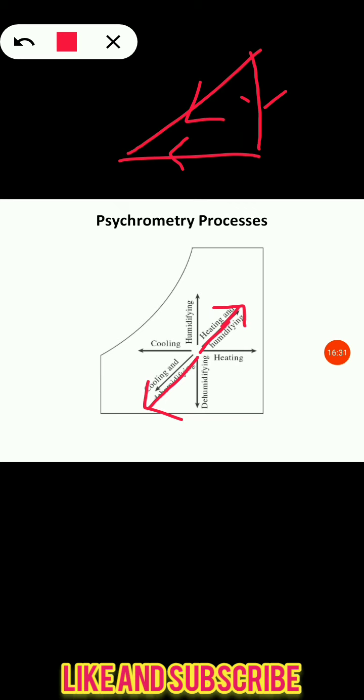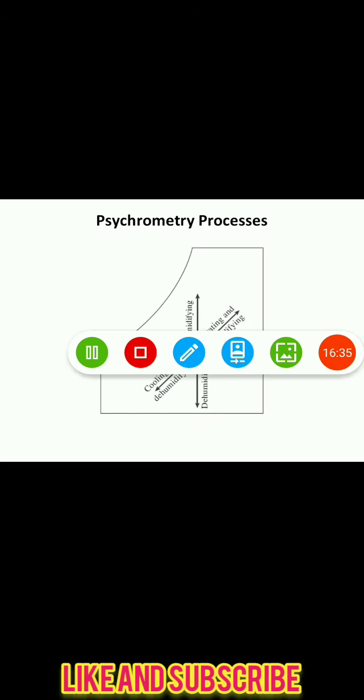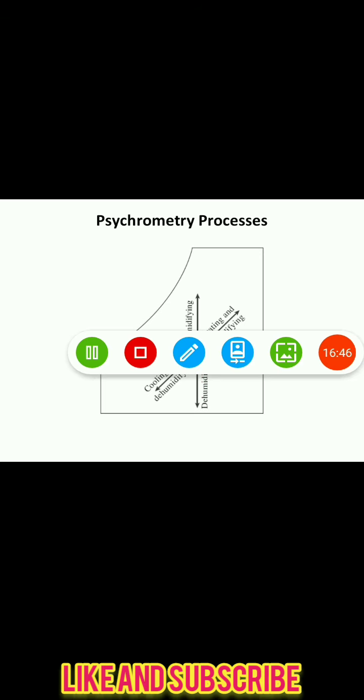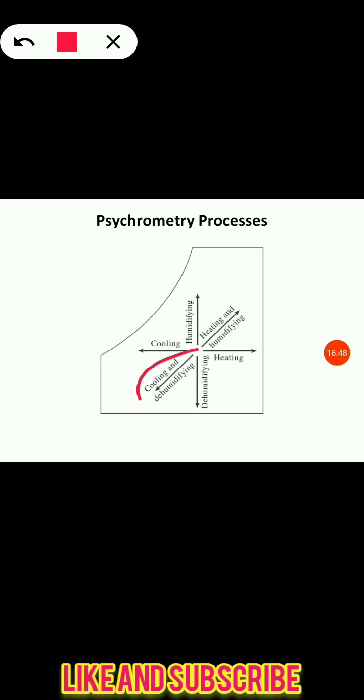Similarly, as you all know, separate humidification and dehumidification processes are not needed in any air conditioning applications. A combination of those processes is needed, such as cooling and dehumidification, and heating and humidification. So these are the psychrometric processes generally carried out in air conditioning equipment for the purpose of human comfort.